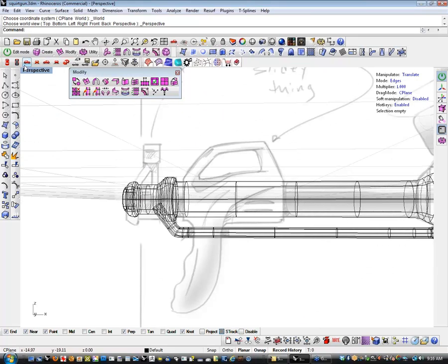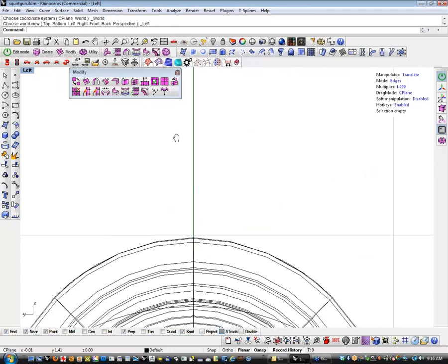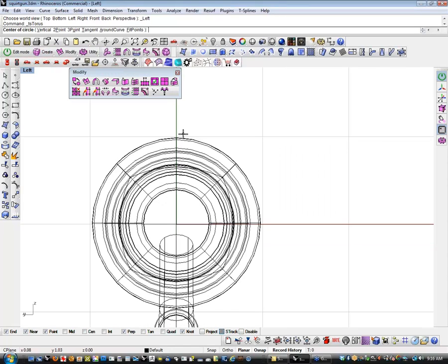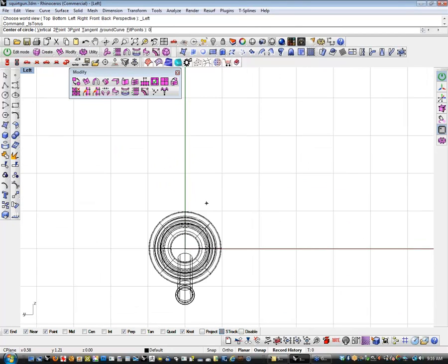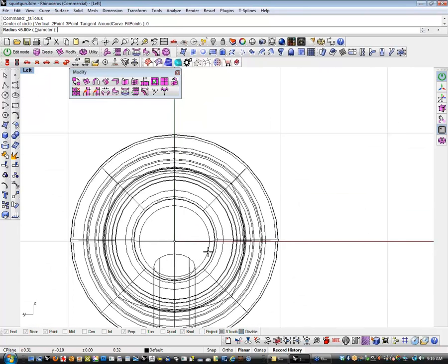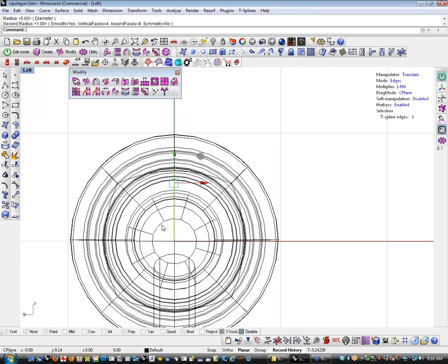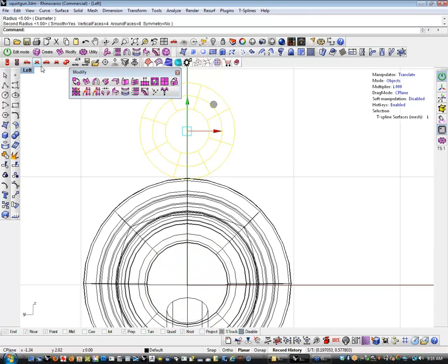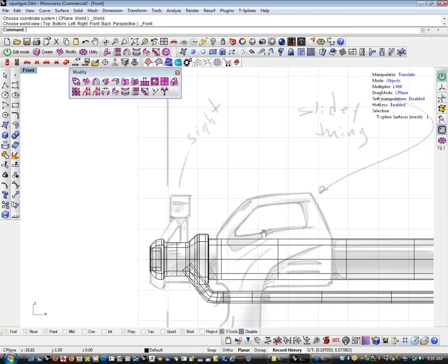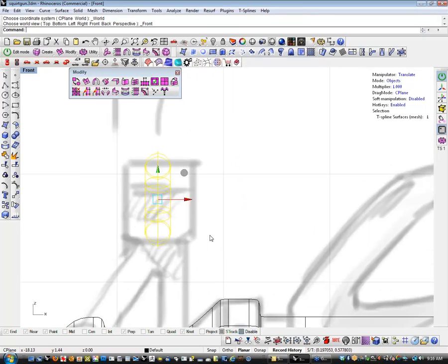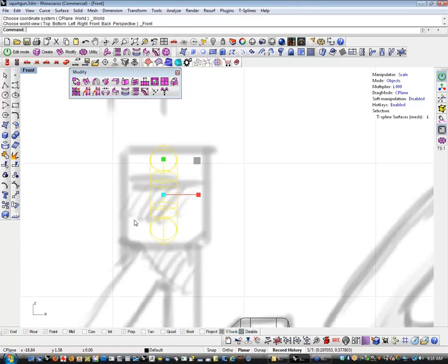Let's address this thing because again it's an easy get, and I'm going to do that again with a primitive. I'm going to use a torus, and I'm going to set that at 0 so that I know that I'm set at 0. Drag out something like that. Pick this object, slide it, come here, slide you up, and let's go find it, it's back here. It's up. I'm going to scale it so that it matches my top and bottom.